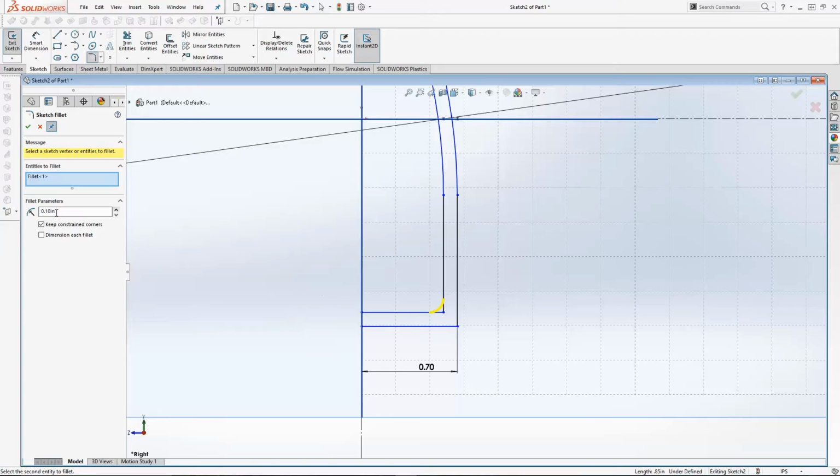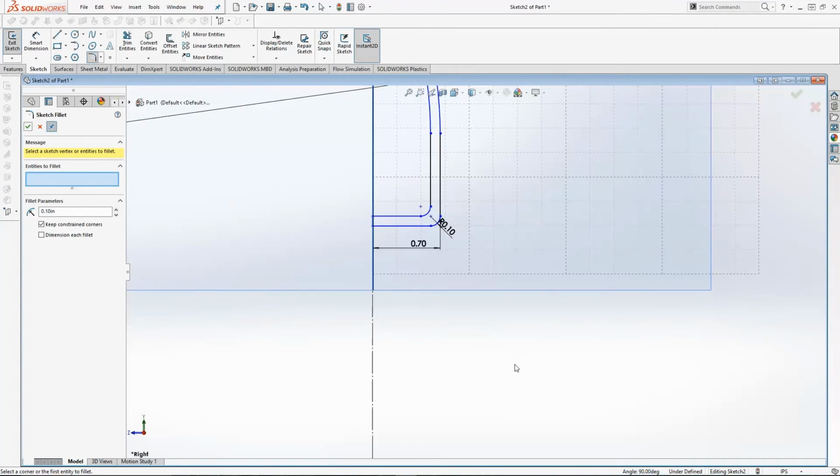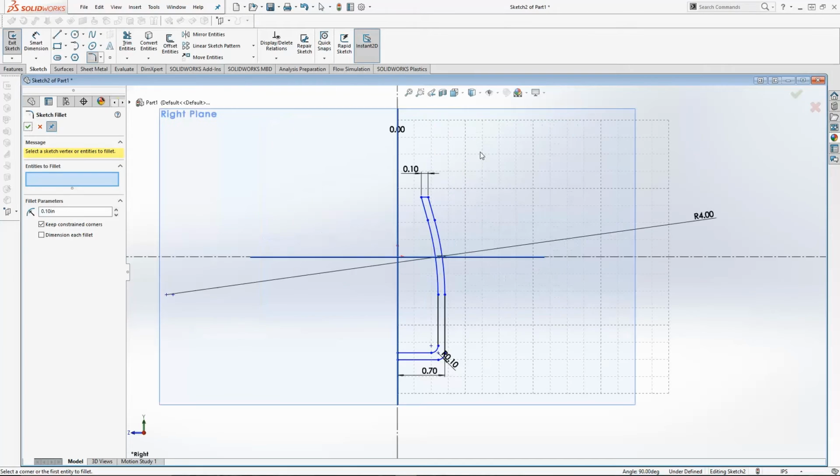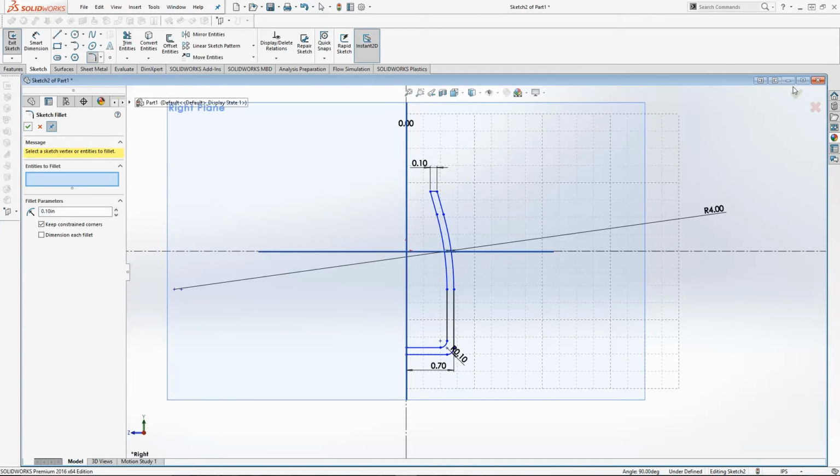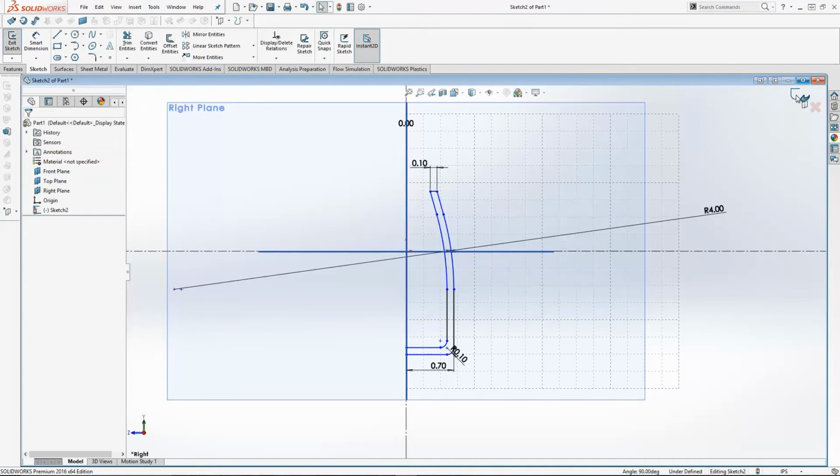So it wasn't letting me add that fillet because the radius was too large. Just make it smaller, and then re-add it. So I'm gonna do that again here. I'm just gonna leave that at 0.1. That's fine and dandy for this. So you can see the shape of the casing that we had before, and we're still only working with one feature, which is really nice. And we're just going to finish this.